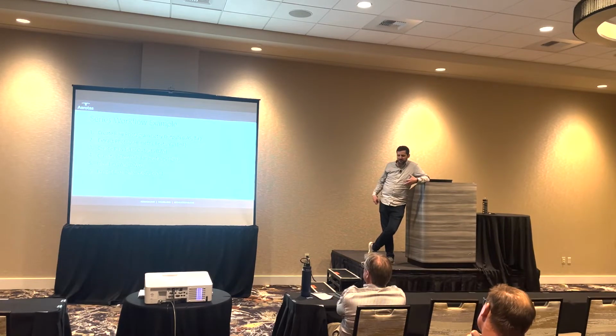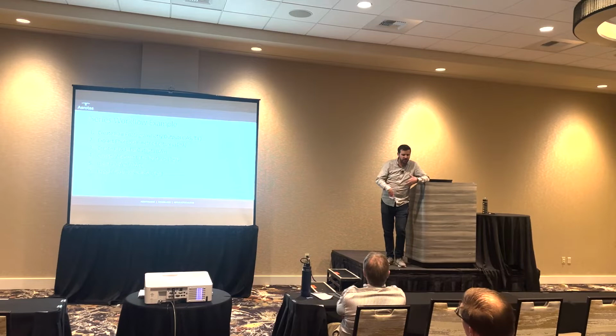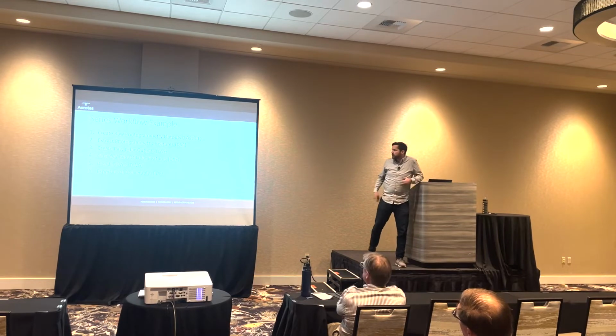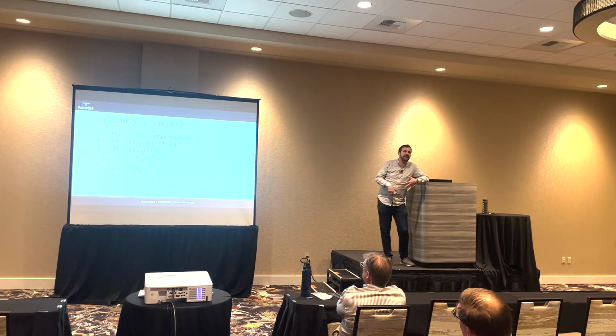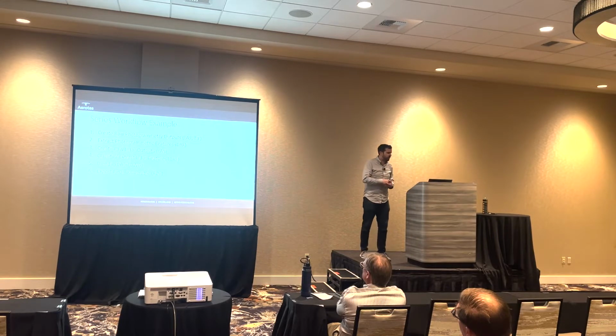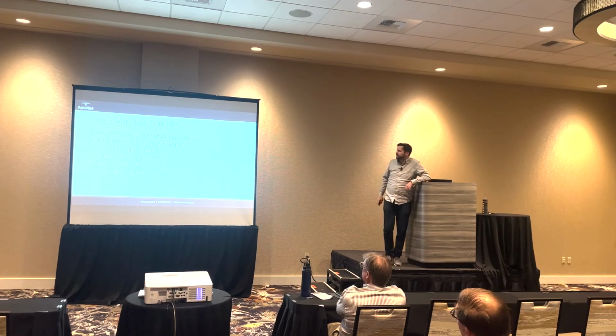That's because photogrammetry, as we talked a lot about yesterday, is typically more accurate. Create your raw LiDAR outputs next, and then, once you know the stuff that you can't get from photogrammetry, use the LiDAR data to extract all the parts that were missing, putting it all into CAD.